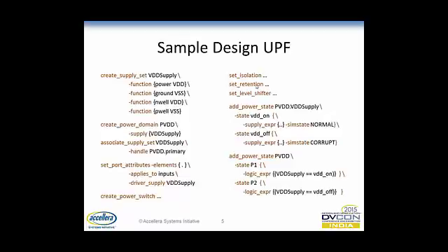Then you have to create level shifter rules if any signal is getting transferred from high voltage to low voltage or vice versa. And then you define what the valid operating modes are for each supply set, and the power modes, in terms of, for each power domain, what the different configurations are when all supply sets are used together. So this is what we typically capture in the Design UPF.